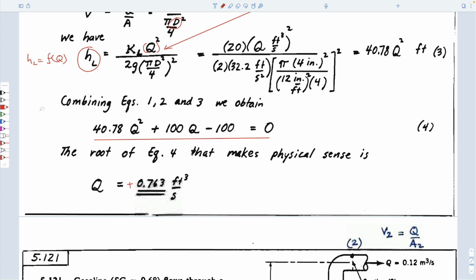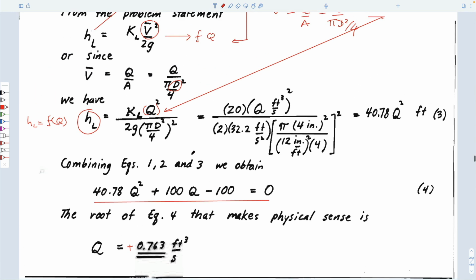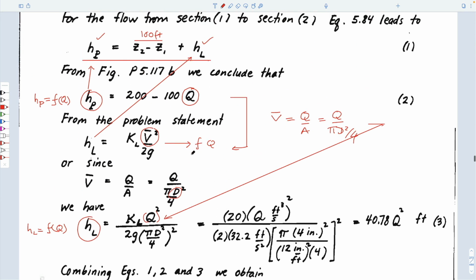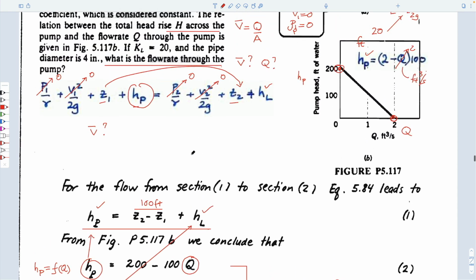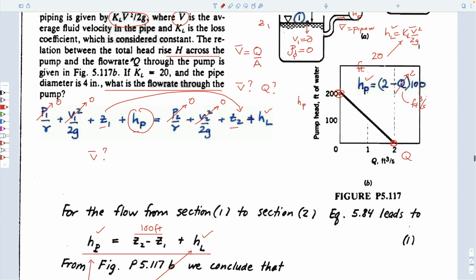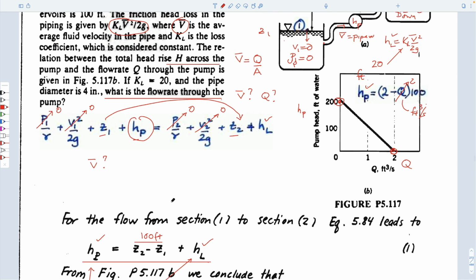So I think the mechanics are more important, obviously more complex than an exam question, but the basic way of doing it is to realize that you need to solve the Bernoulli equation. You know most of the Bernoulli equation except for 4 terms. 2 of the terms are the elevation drop. 1 of the terms is the pump equation here. 1 of the terms is the head loss, which is given by the velocity of flow through the system, this term here.